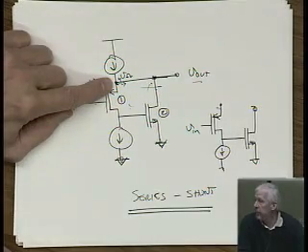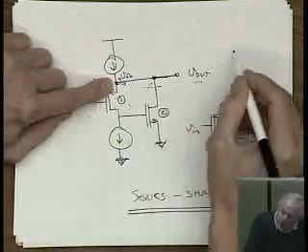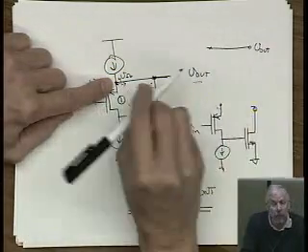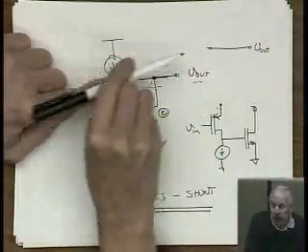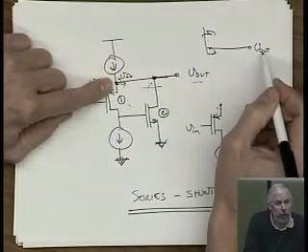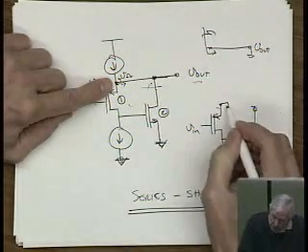What is it? Short. Okay, why is that? Well, you're looking in and you're seeing, so here's the feedback. It's a wire, right? And it's V out on the other side of this thing. So looking in from this side, we're looking into a voltage source, which is going to look like a short circuit. So basically, it's like a short. So this guy we just short.